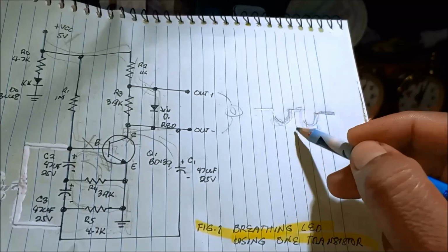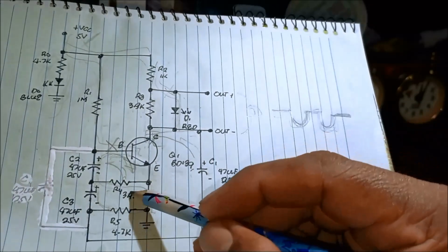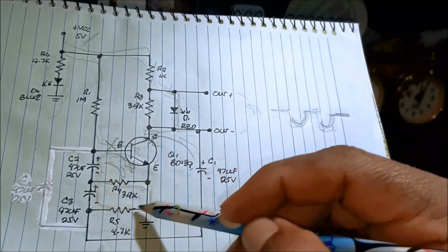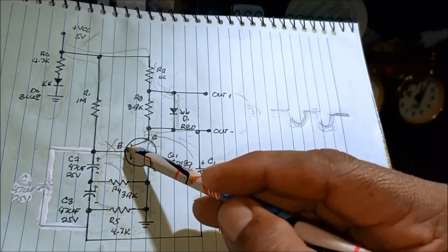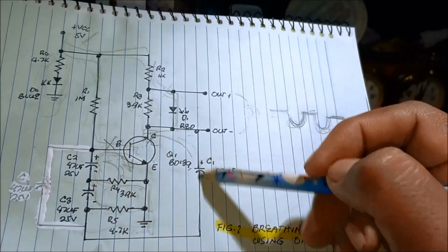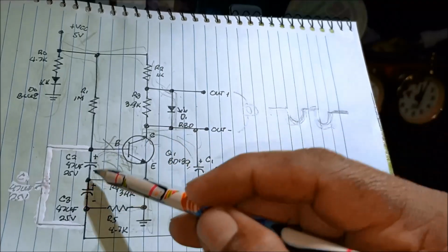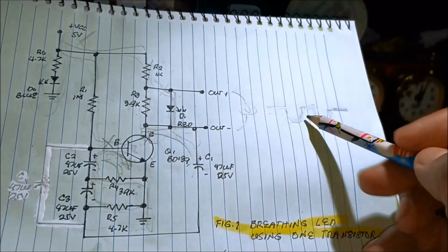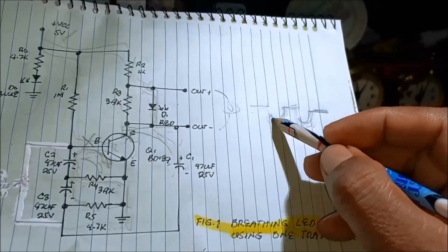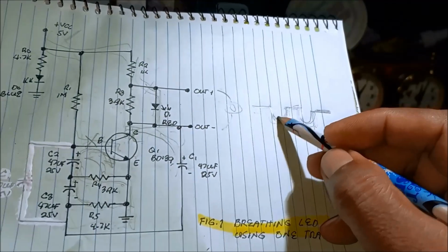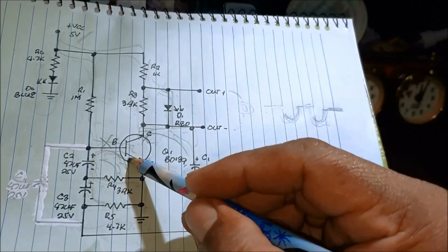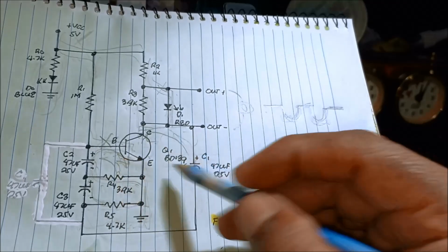So it is an oscillator because of the RC network, the two RC networks at the input. As we can see here, we have the feedback from the output to the input. That's why it oscillates, and the oscillation is caused by the internal noise of the circuit.